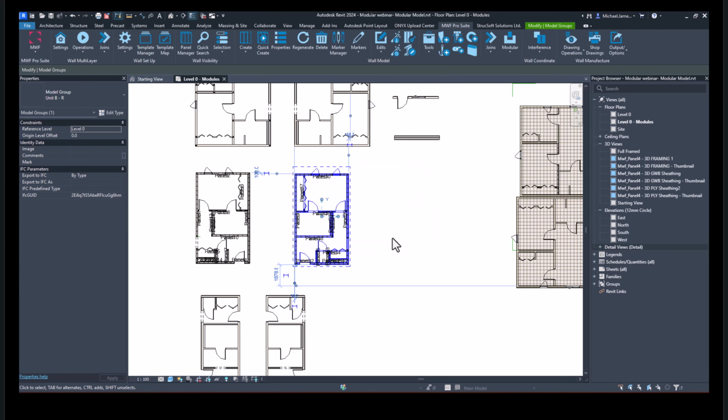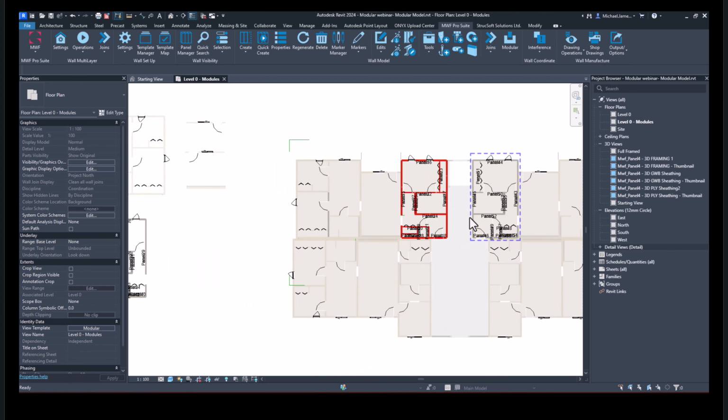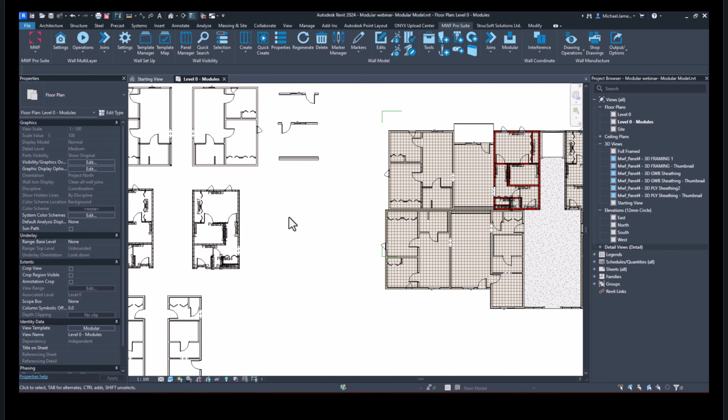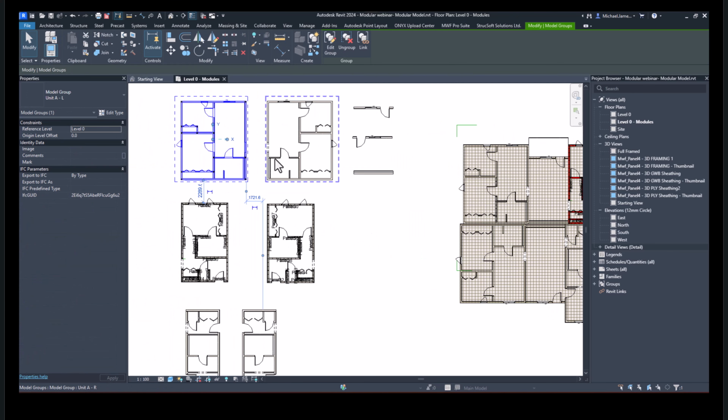Once complete, we can take a look at that framed group, and you can see we've copied the properties from that selected group, and we continued the numbering from the previous panels. You can see that it has framed these with the same kind of settings. So as well as copying members from panels, we can also match properties on panels as well. To demonstrate this, I will frame one of the other groups that are available.